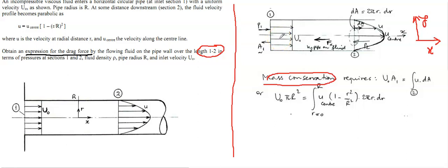One is the fluid, which is putting some force on the pipe, and the other is the pipe on the fluid. So Fx, this is the positive direction. You see the fluid is going this way, so the force is in this direction. So there should be an opposite force Fx in the opposite direction by the pipe on the fluid.